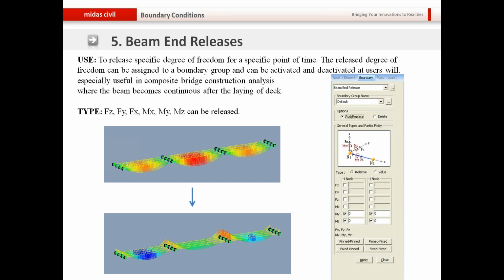In the precast girder bridge, let's say it's a 3-span continuous precast girder bridge. In stage 1, we install the girders of span 1. In stage 2, we install the girders of span 2. In stage 3, we install the girders of span 3. And in that stage, these 3 girders in 3 different spans are simply supported.